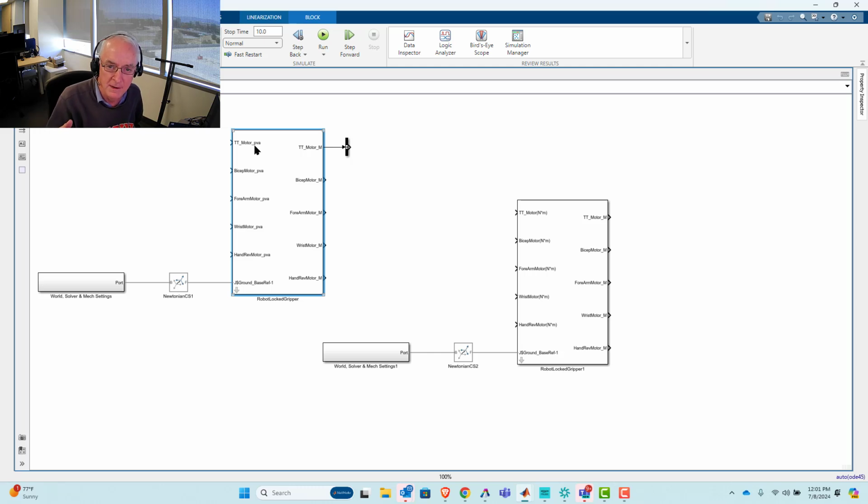It means that we send in a 3-component signal, and it's essentially position, velocity, and acceleration. I call it motion because all 3 signals need to, of course, be constrained such that V will be the first derivative of P with regard to time, and A, of course, would be the first derivative of V. Okay, so anyways, let's go ahead and hit run.